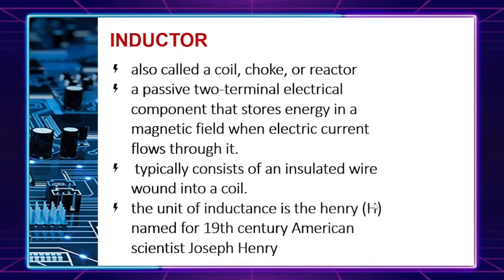Okay. So we are done with the capacitors. What are its applications or function? Even the different types based on its schematic symbol and the actual values. Aside from that, we discussed also the different classifications of this component, starting from electrolytic, mica, ceramic, paper. So we can recognize the difference of these components based on its dielectric material.